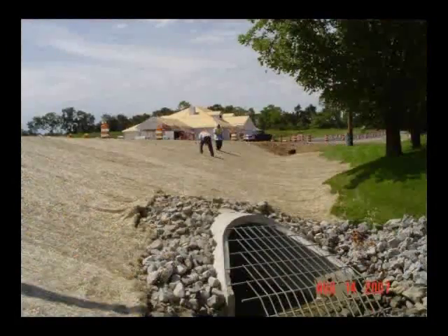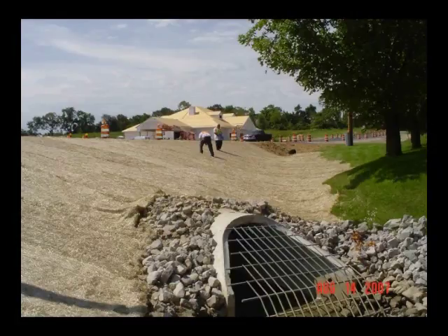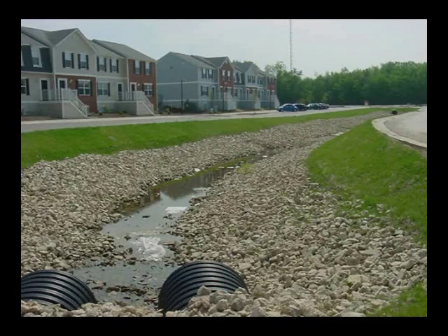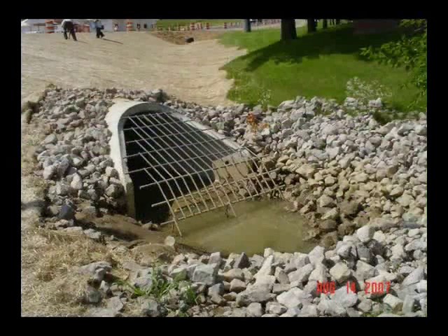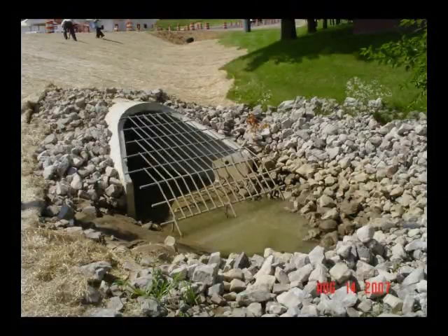To keep the spaces between riprap structures free of sediment, bare soil upslope of riprap should be stabilized with erosion control blankets, sod or seed and mulch, or the riprap must be otherwise protected by means of temporary sediment controls. If placing riprap requires the reconfiguration of banks, slopes, or channels, filter fabric and riprap should be placed immediately after grading. The filter fabric and riprap should be keyed in at the top and bottom of the slope. The riprap should be installed before any concentrated discharge occurs.